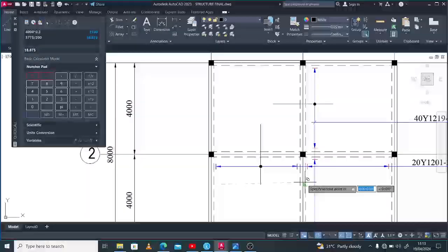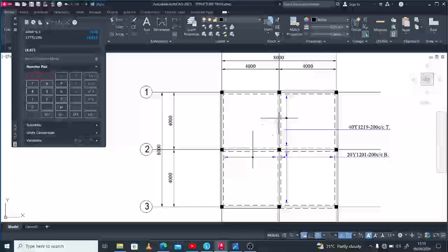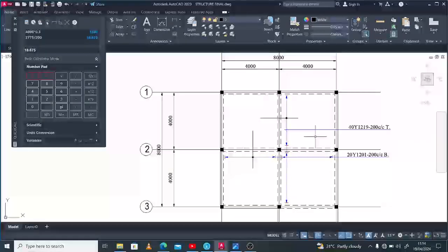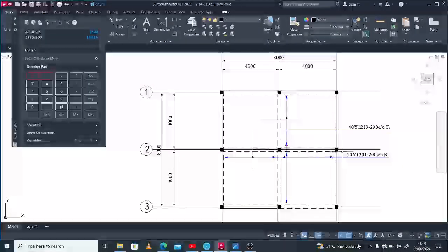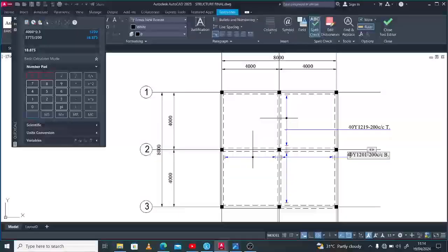As in the case of what I explained concerning this reinforcement above, if you have a varying dimension of this slab, then it might not be sufficient to cater for this support of this slab. So you might have to create a separate reinforcement for that support. So this will be 40, and this one also will be top.